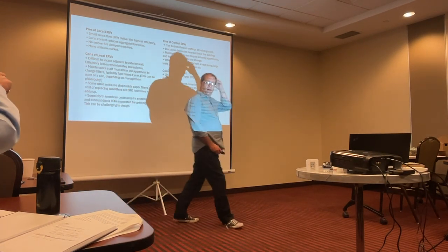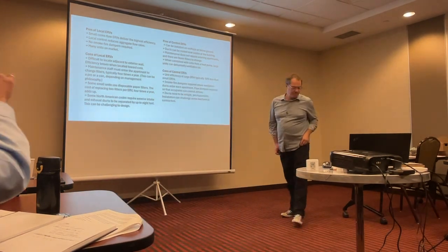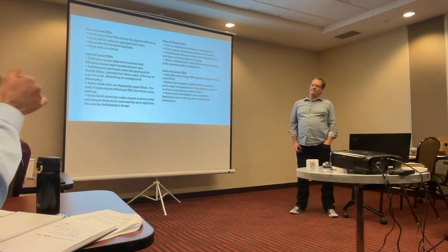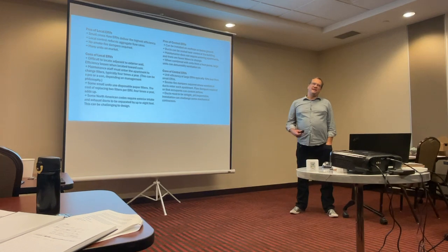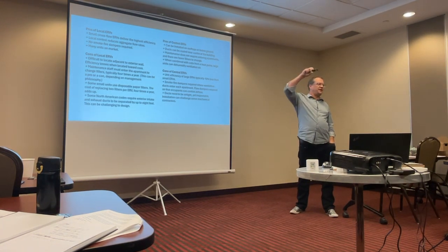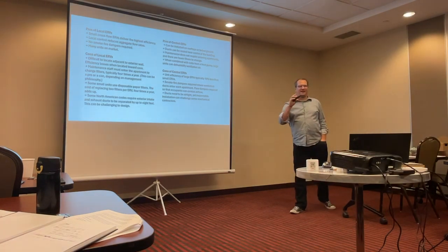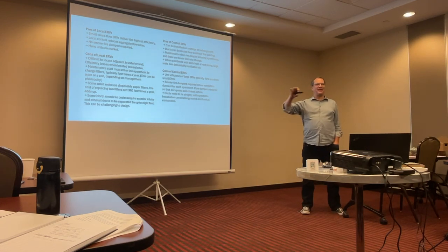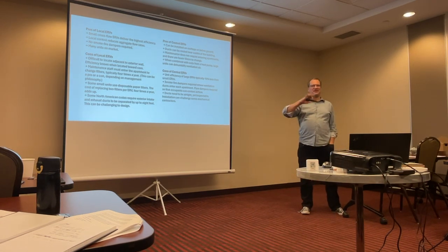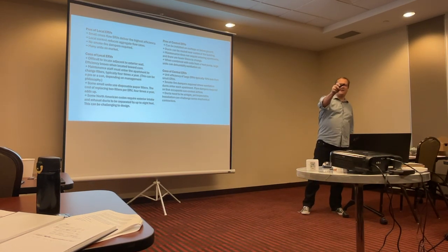I think it's important, whereas not flat out, but jurisdiction specific, we should flag it so we can look into it. And there is a way to design around smoke fire dampers through where you bring your supply and return. I'm not going to get into that. That's kind of a gray area, Jedi level mechanical engineer stuff, and if you don't have a Jedi mechanical engineer, don't go there.